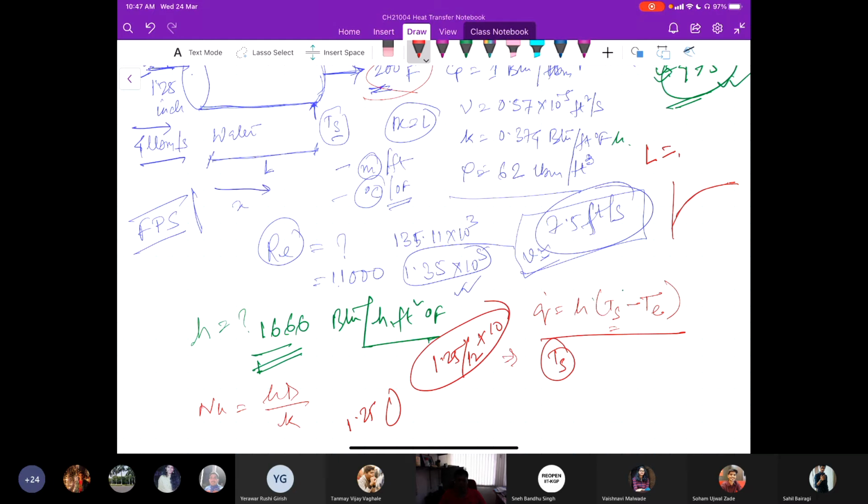negligible, not even 1 foot, compared to the value that is required to be considered fully developed turbulent flow. And that is why you are safely applying the Dittus-Boelter equation. It is 10 times d that we consider for the turbulent entry length in case of fully turbulent flow.